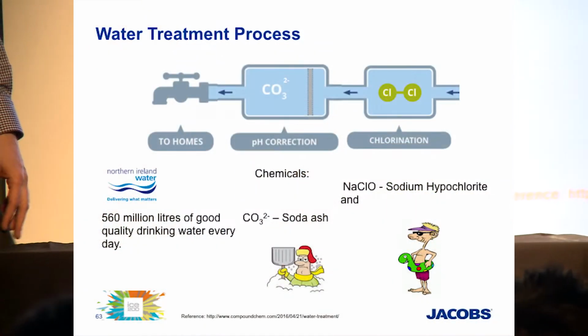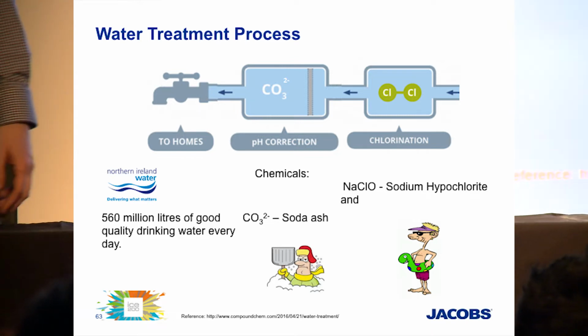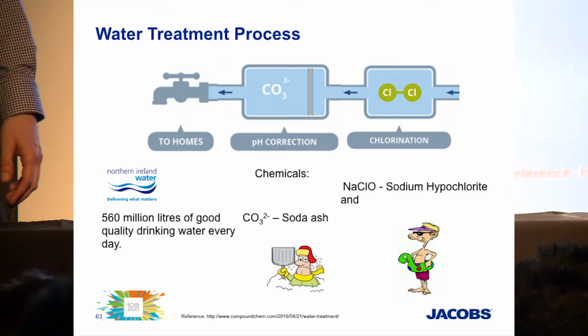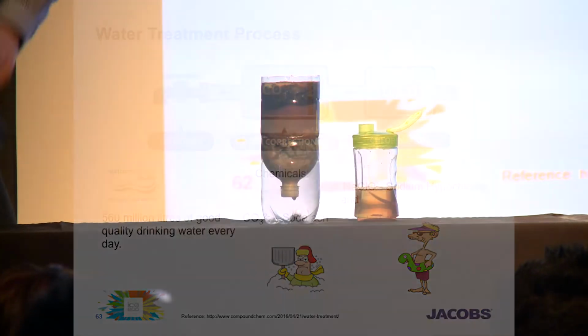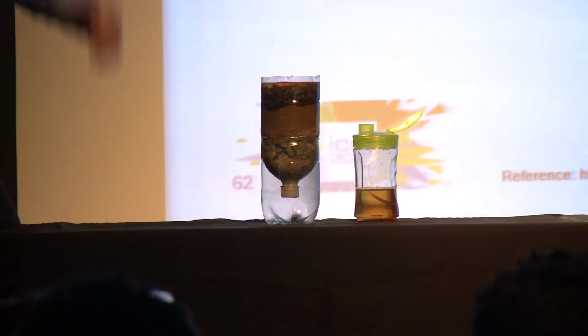After this, the water is disinfected with chlorine, something similar to your local swimming pool. And this helps kill any bacteria, viruses. It then sometimes will be dosed with soda ash. This brings the pH of the water up to 7, which is suitable for drinking.